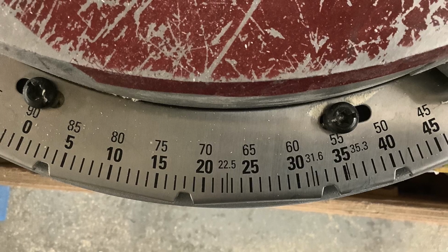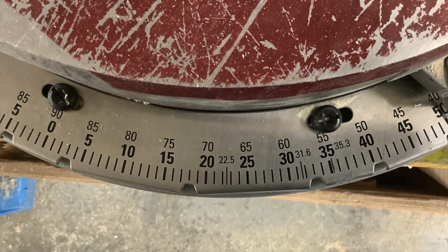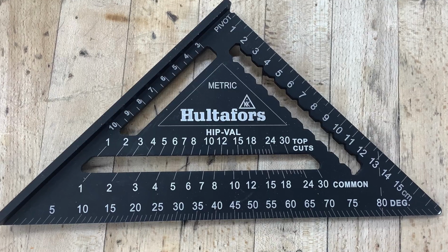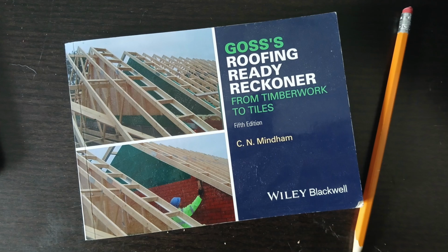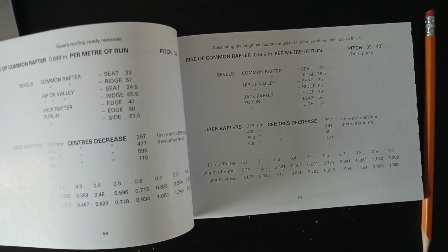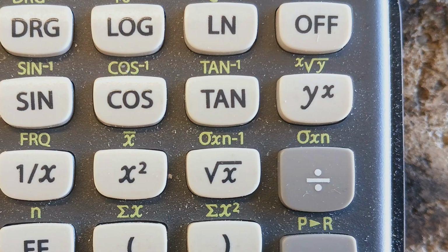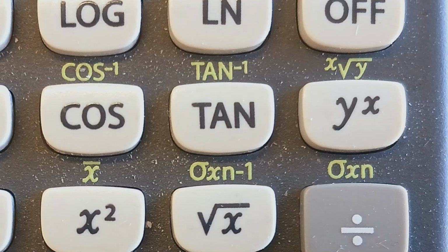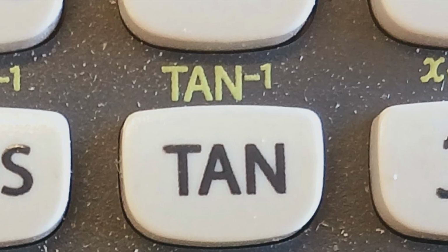In the UK and Scandinavia, construction plans use degrees to specify roof slopes. This simplifies angle cutting with miter saws and marking with speed squares, but it complicates using the step-off method or calculating a line length. British carpenters use this reference book to convert degrees to rise and run and to find line lengths. But with a couple of keys on a pocket calculator, you can quickly find all the information you need. The tan key will convert degrees to the tangent ratio, which is rise per single unit of run. And the arctangent, or tan to the -1 key, will convert any tangent to degrees.